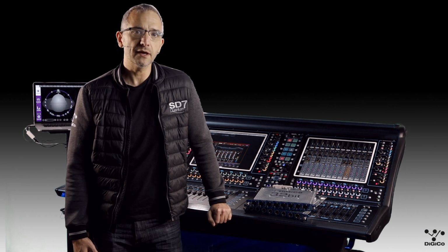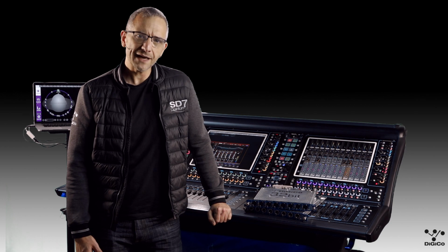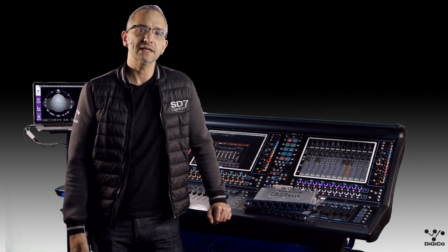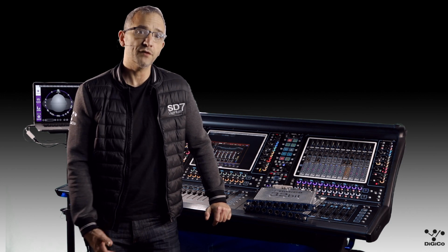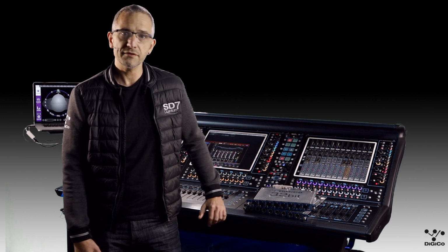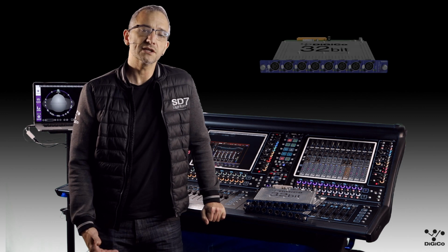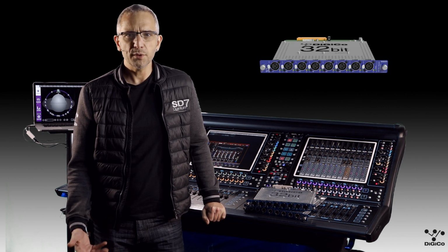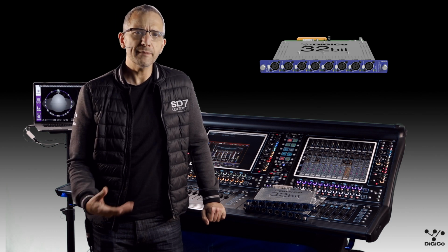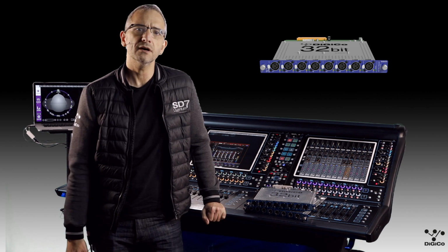In this in-depth video, we're going to take a look at DiGiCo's 32-bit converter options. Our flagship A to D converters have been available as an SD rack card option since 2017, with the D2A output card following a year later. And now, the local I/O of the new Quantum 338 console, launched this year at NAMM, features 32-bit technology on its local I/O. With a 24-bit audio transport between the SD racks and the SD and Quantum engines, we've been asked how this higher bit depth works with the consoles and what the advantages are.